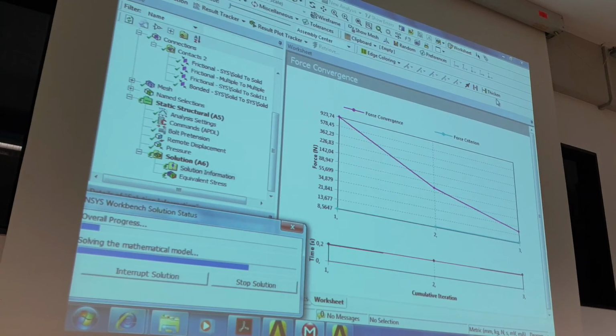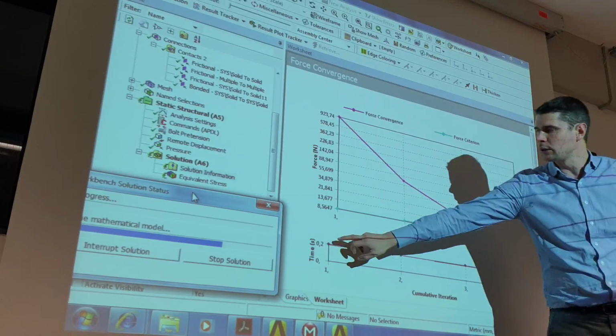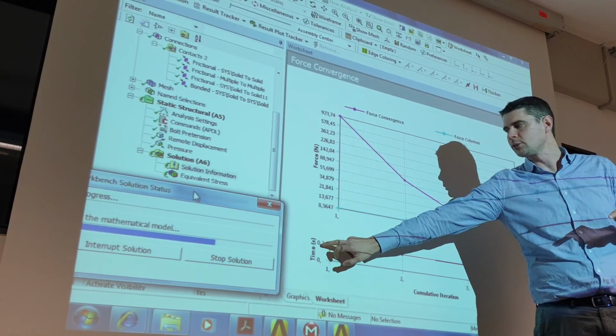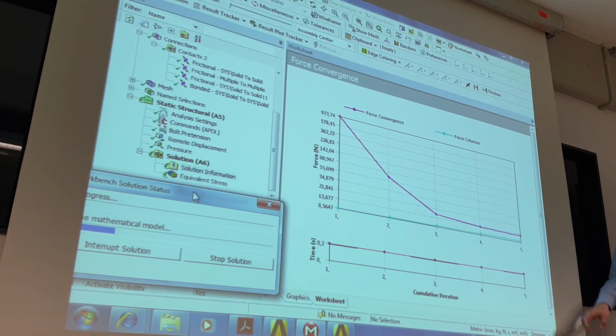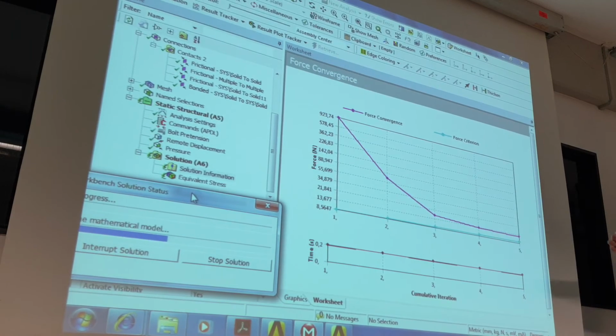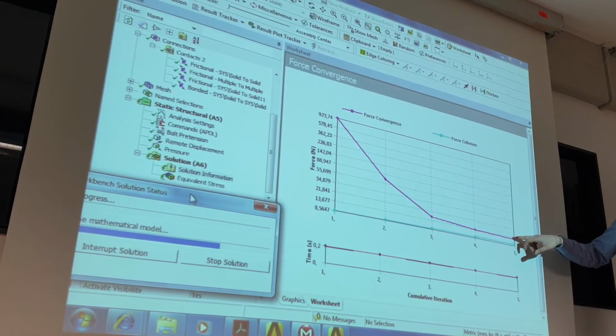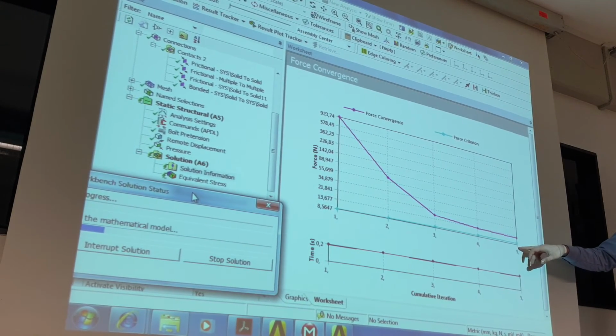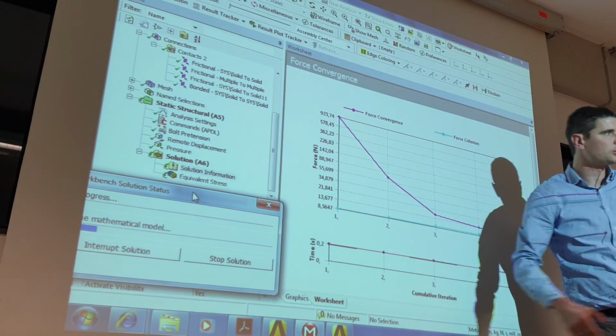Okay, going to what we see now, this convergence report. It's like soccer now, yes? See, our hope is that the red line goes under the blue lines. If it happens, then we found the solution. So, look what's happened. The program tried to calculate 0.2 seconds, yes? 1 second is 8 kilonewton. It means the program tried to calculate 8.6 kilonewton. So, this is error. That is okay. This is my actual error. It means if my error is less than the maximum error allowed, then I found the solution for 0.2 seconds.